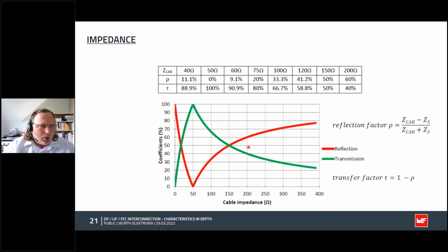However, it can already be seen here that our system is balanced with an impedance of 50 ohms. With this impedance, we have almost no reflections. You can see it here, and a signal of almost 100%. The more the impedance varies, the more important the reflection becomes. This is why impedance matching is so important. After all, we want to transmit the maximum of the signal.